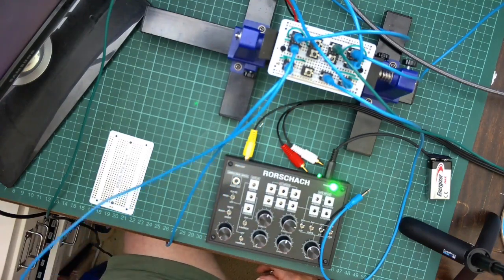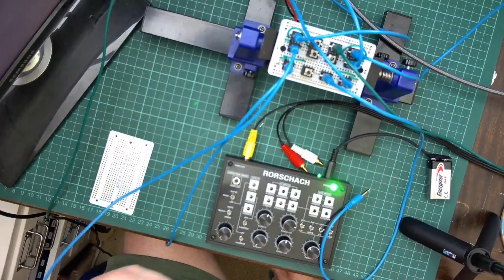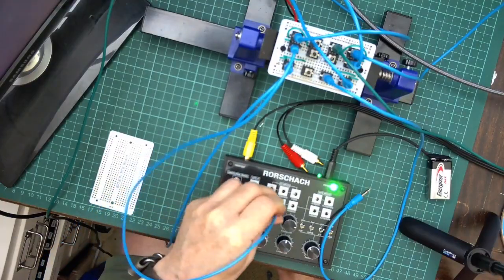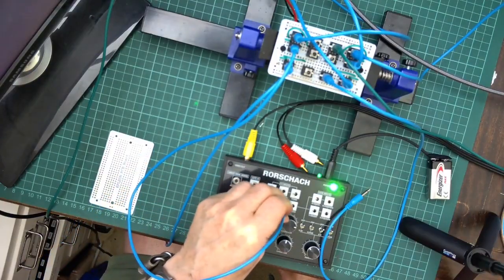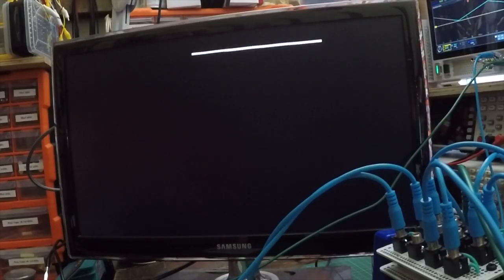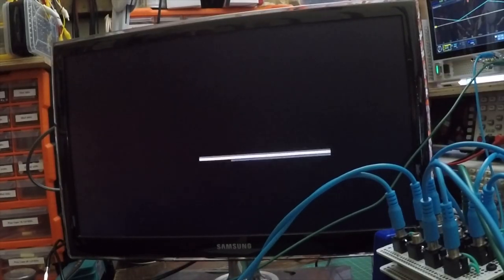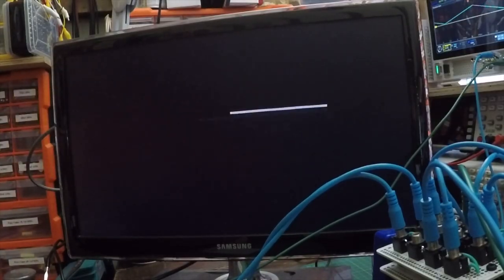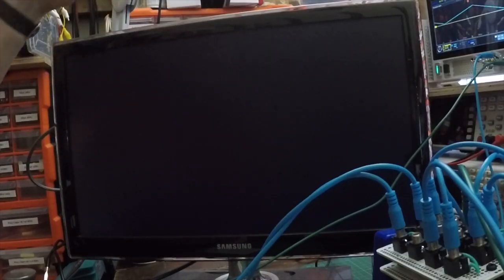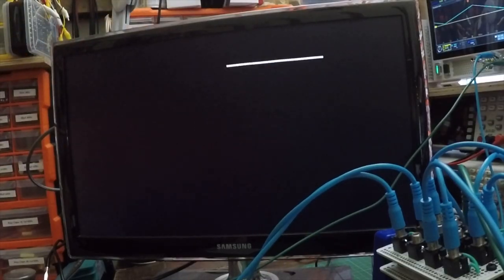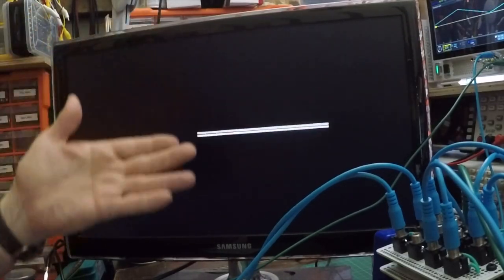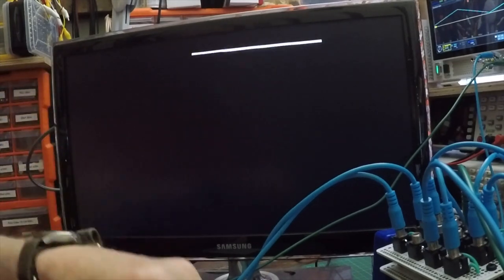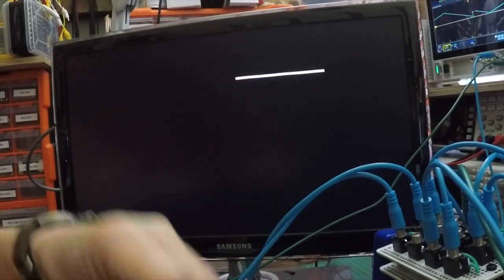Let's put an unattenuated signal in. So this is what it would look like just with a normal Eurorack modulation signal going in. You can see that the system hangs at the top where that waveform is now above that 5 volts or below the 0 volts that Rorschach can tolerate. So we're not using the full range of the Eurorack, in this case LFO.